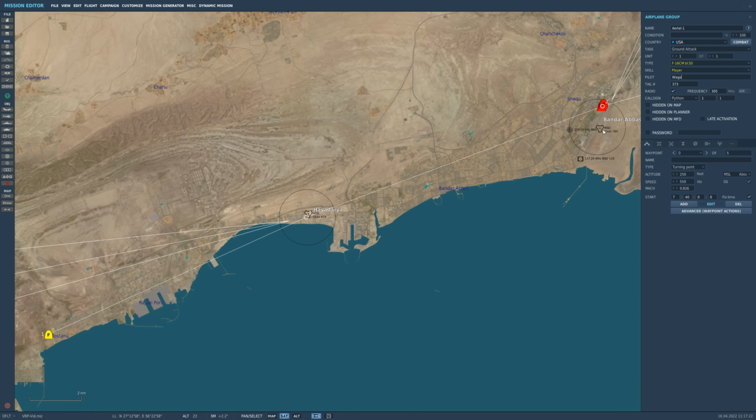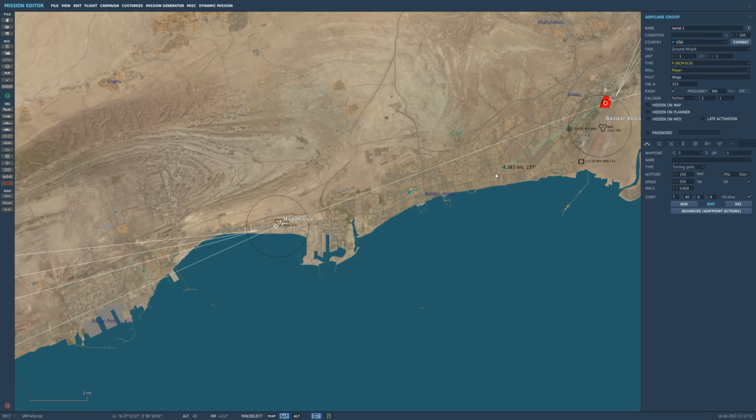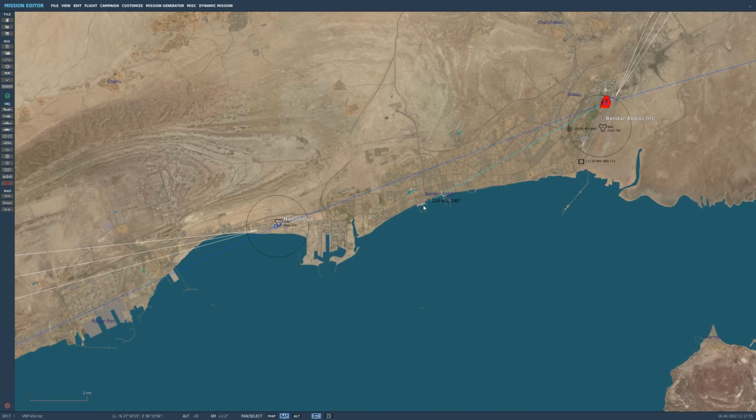The key to remember about VRP is that the selected steer point is also going to be the target location. So in this case, we'll select the steer point / target, and then based on an inputted bearing and range, we'll create a reference point from that. Again, we'll use the ruler tool, and we'll make my RP at about 240 degrees at 7.2 nautical miles. And again, we'll put a pull-up point somewhere between them.